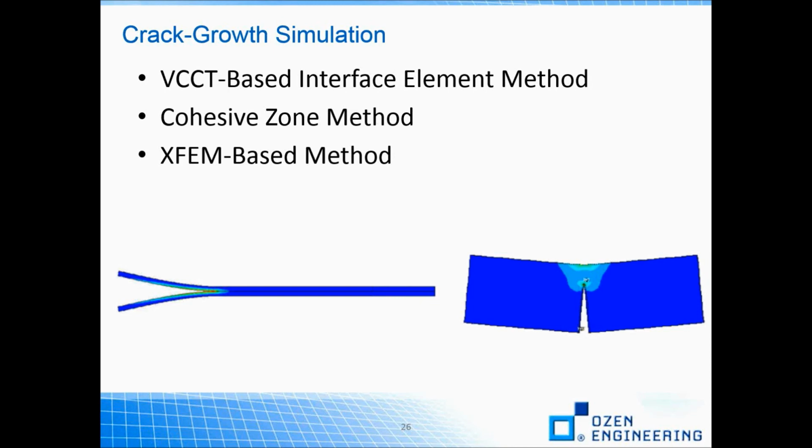The VCCT-based crack growth simulation and cohesive zone modeling can be used for crack growth along interfaces, that is the predefined interfaces. And the XFEM-based crack growth simulation technique simulates crack growth along an arbitrary path and strictly in linear elastic homogeneous materials. And we will have actually two webinars, specifically one on the XFEM method and one on cohesive zone and VCCT-based interface element crack propagation techniques.